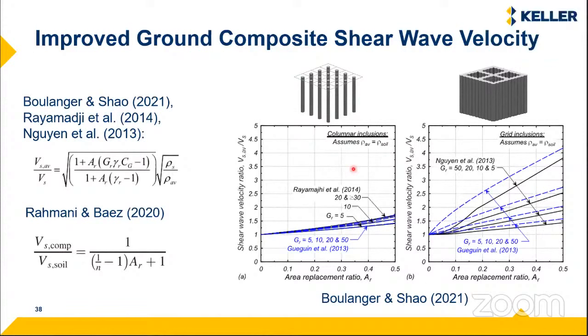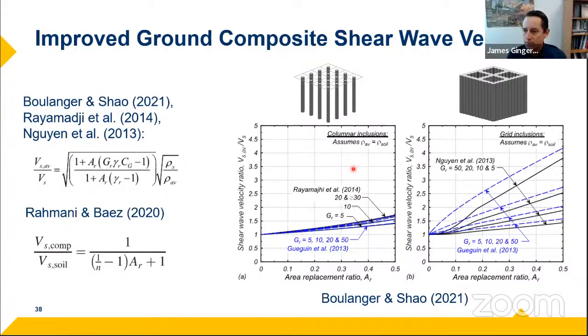Okay. Our next question is, what are your opinions on EQ drains? Yeah, so earthquake drains is a technique that I didn't cover here, but it's basically a method where you install with a mandrel a sort of larger diameter wick drain. It allows for water to be drained out during the earthquake loading so that the pore water pressure doesn't build up. In some parts of the country, it's very commonly used and effective.